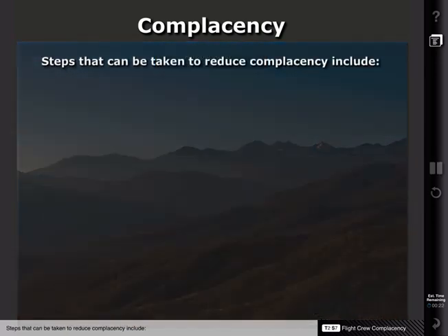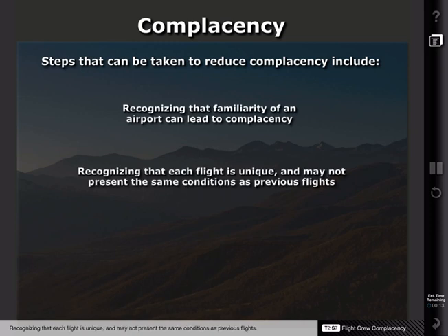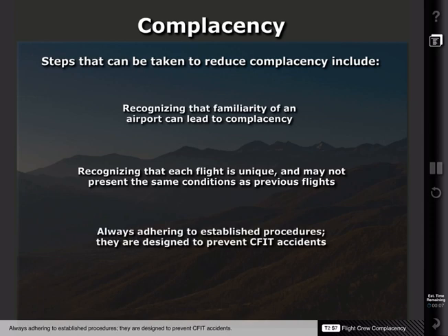Steps that can be taken to reduce complacency include recognizing that familiarity of an airport can lead to complacency. Recognizing that each flight is unique and may not present the same conditions as previous flights. And always adhering to established procedures. They are designed to prevent CFIT accidents.